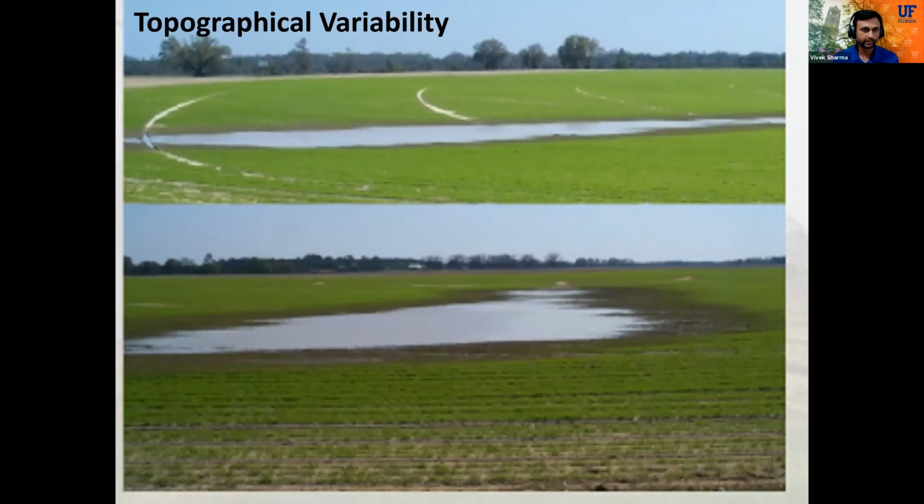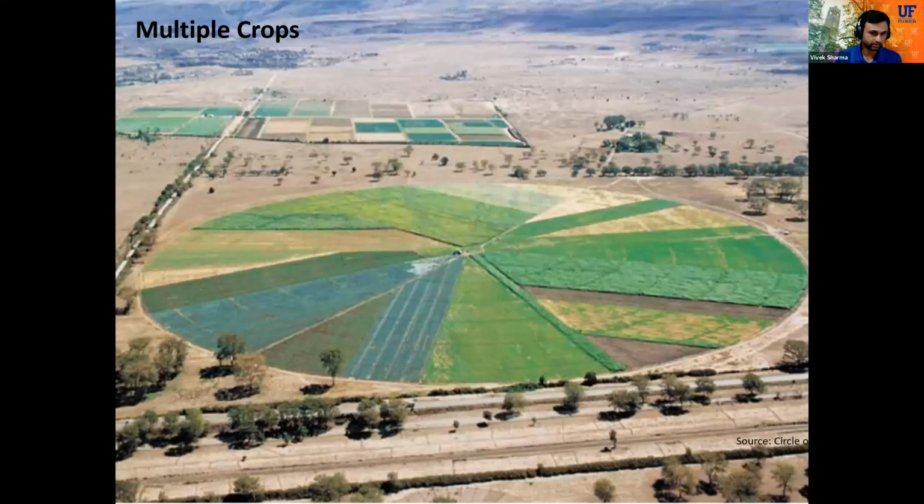The other condition might be multiple crops. If multiple crops are grown under the same pivot or the same irrigation system, for example, in a Florida situation, one half of the pivot is corn and the other half is peanut. Both have a different irrigation requirement and a different growth stage. So the variable rate irrigation system allows us to change the prescription based upon the crops also.